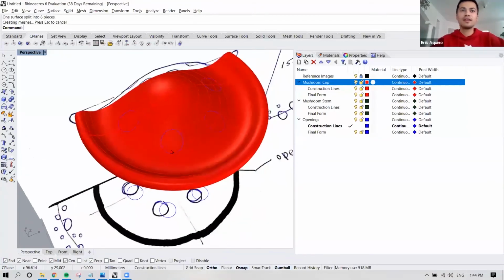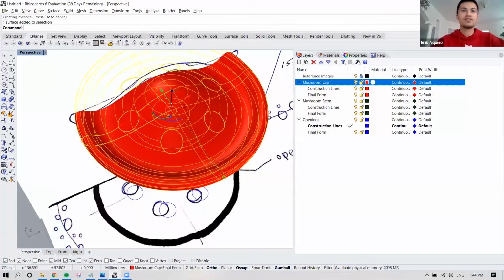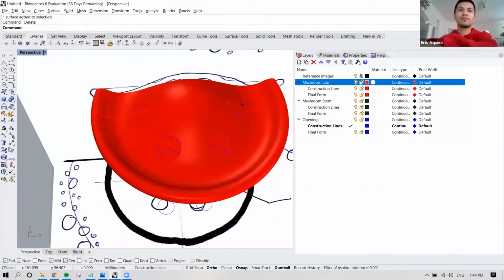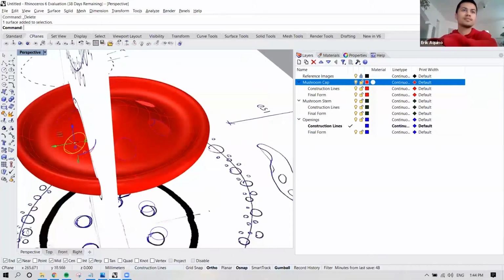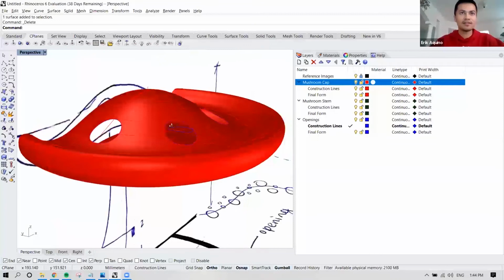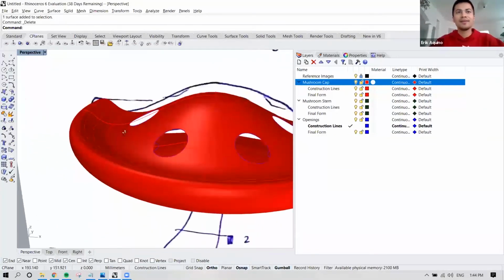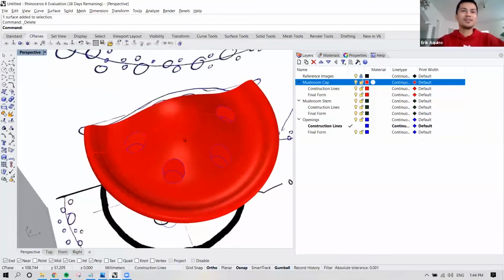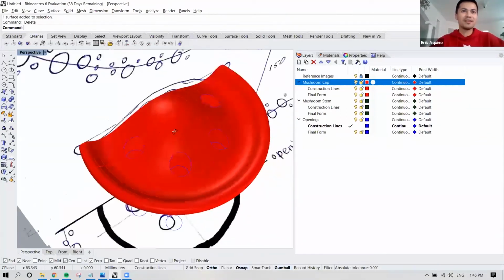It doesn't look like anything has changed, but when you select the surface, it's been broken up now. And I can delete these and reveal or create my openings for this object. And you can see that now it has an interior, and from there you could create your spaces and programs within your building.